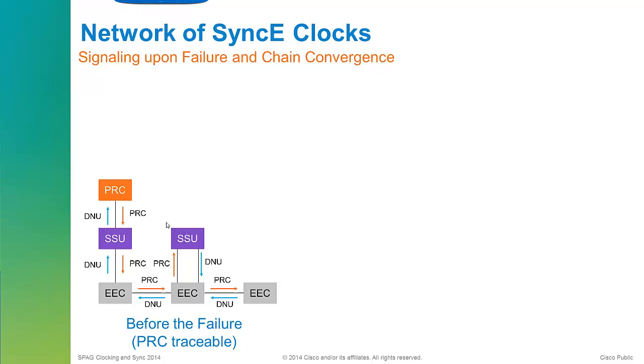And the way that it works is, in this case we have a primary reference clock here, which is the highest quality reference clock that we can have, and we have a Synchronous Ethernet circuit connected to an SSU, which is the next quality level down, and that has an Ethernet circuit which is connected to your ordinary router, which normally is an Ethernet equipment clock. It's an EEC, that's a normal router here down the bottom. And what happens is the primary reference clock, when it comes up, it says, well, I'm a primary reference clock, so it becomes the clock master, if you like, the clock source of this circuit, and this guy then takes the frequency from that link, and it says, oh, this guy's PRC, I'm going to listen to that because obviously it's a primary reference clock. I'll take my synchronization sources from there.